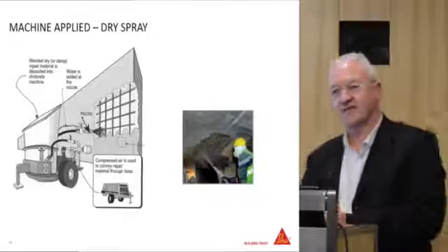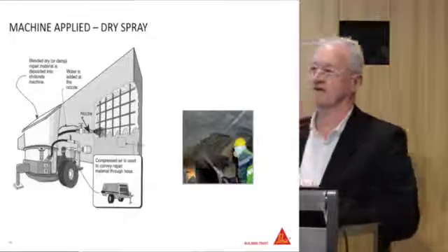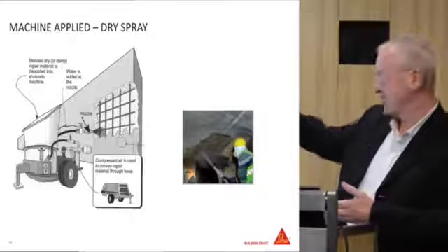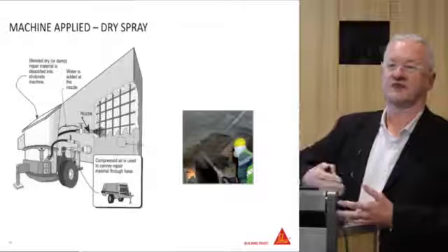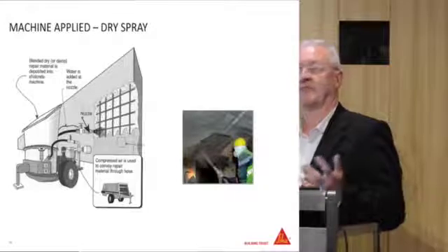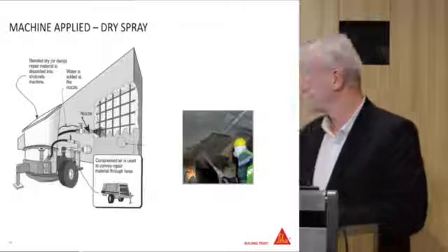They're moving around, adjusting the nozzle to get that material in. Once you get beyond the surface of the main structure, it's just trimmed off, and then you can apply your levelling mortar or anything else, and afterwards protective coatings.